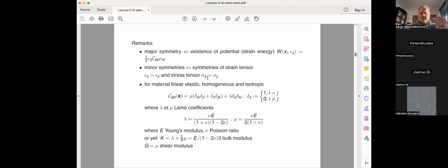In other words, you have something called a linear elastic, homogeneous, and isotropic material. What that means is that you have a response that is the same in each and every direction that you might have chosen. Typically, wood is an orthotropic material because the fibers of the wood, let's say of the trunk of the tree, go in one direction. Then perpendicular to that, you don't have the same resistance because you don't have those fibers. And many composite materials with long fibers have the same principle. You have a resistance along the fiber and then a different resistance perpendicular to it. So that is called an orthotropic material.